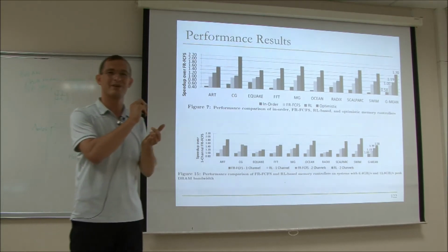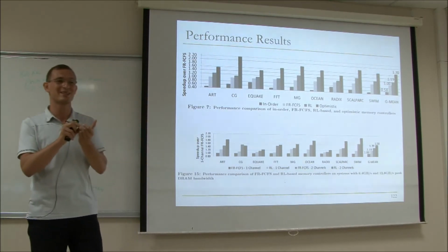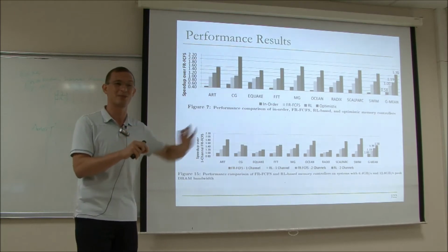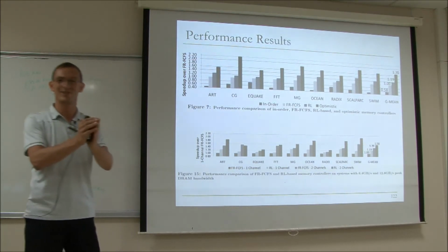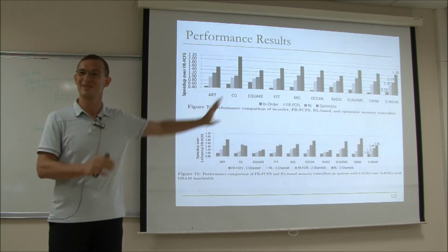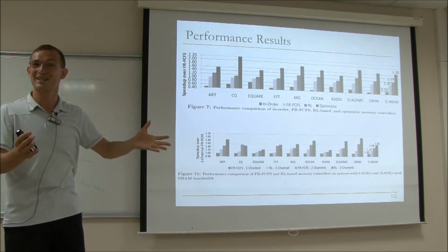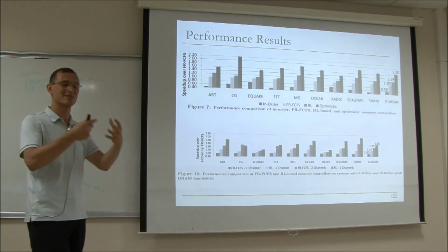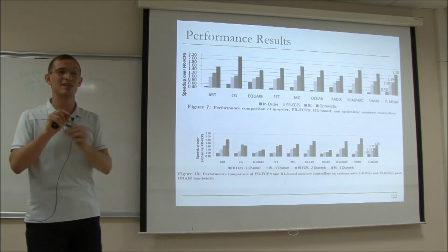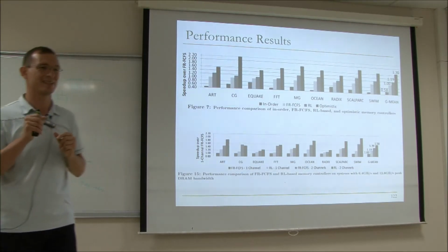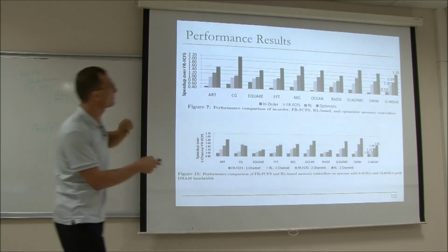Whenever I talk to designers about this, the designers are not necessarily comfortable because it's a black box, right? With the row hit first scheduling policy, they know how it's going to work. Whereas with this, it's a black box, and they haven't decided. Even though there is high-level theoretical intuition, there is no immediate intuition that the designer gets. It's not a row hit or row miss. Okay, what are the performance results?